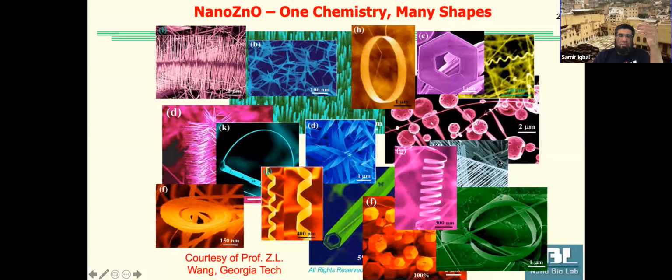All right, so now this is a very interesting figure. Yeah, colors, we have done false colors on this. Actually, they all would be electron microscope pictures. But the thing is, it's all one material. It's zinc oxide, ZnO. But by changing the synthesis conditions, by changing the atmosphere, by changing the other gases in that chamber, you can synthesize many different forms and shapes of the same material. Same zinc oxide, but at nanoscale, you can taper, change, direct its growth in so many fantastic ways.